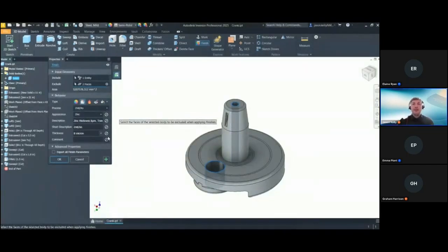What we've also got is the option to disable parameters. You'll see next to the parameters down this right hand side, you've got some disable buttons. Previously, when you exported a parameter in the finish command, it exported into your parameters dialog box with all of these properties included. Each of the different types has different properties available. So what they've done now is disable the option so that if you don't want to pull through the comments or the description, you're not clogging up your parameters. You're only pulling through the relevant data that you want. And you'll also see there's an option now to export all of the finish parameters.